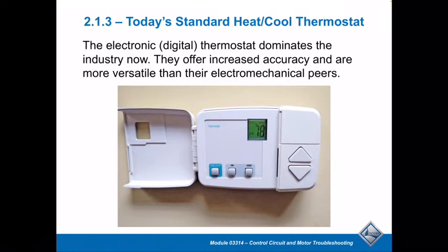If you have a thermostat that does have an automatic changeover function, that means if you set it to auto, and the temperature in the building falls lower than the set point, it would energize the heating. And if it got too warm, it would turn the cooling on. Commercially, sometimes people will do that. Residentially, it's not typical that most people are going to do auto. Most people are going to just set the mode, but it really depends on the customer how they want to do that.